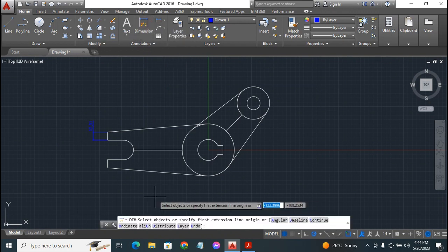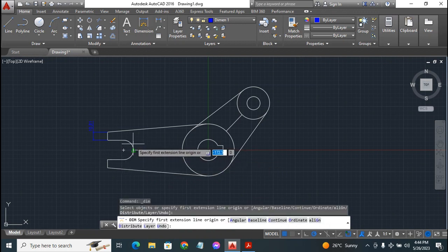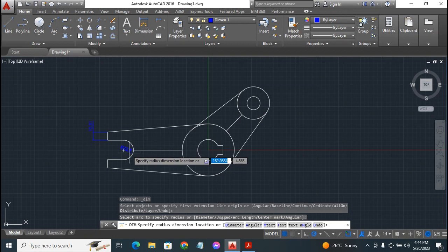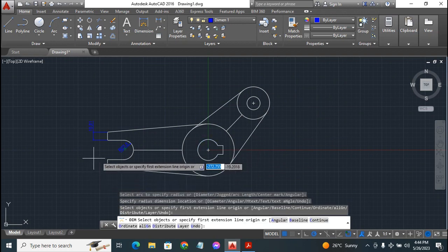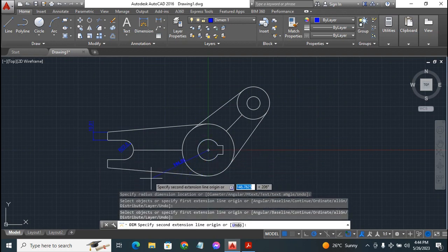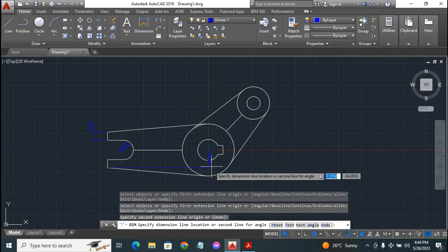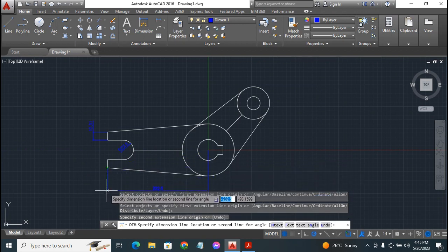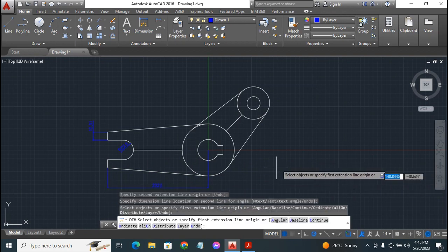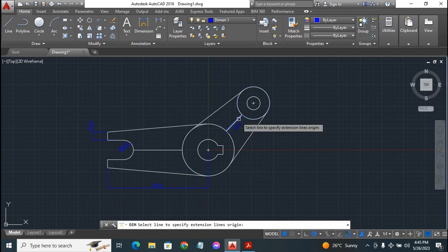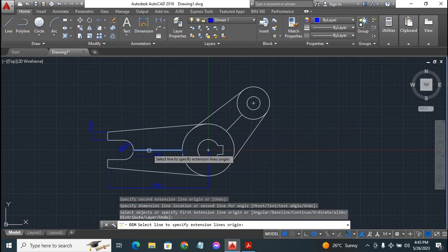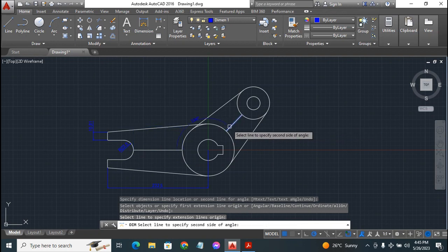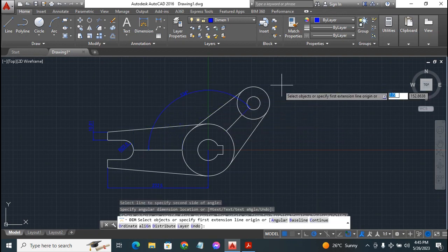So I'll click on dimension. Next up, I want to put in the dimension of this mid circle, so I'll click on it. That's correct, 22.5. Let's put in the entire dimension, the distance for this entire length, from that center right to this point: 232.5. That's correct. Now let's put in this angle, the angle of 134 degrees. Click on this. Right there, 134 degrees. That's correct.